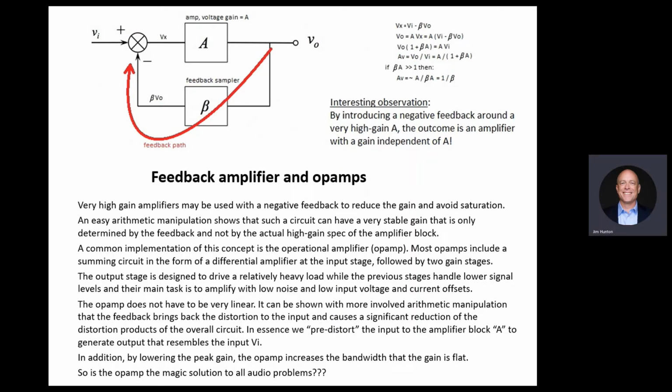All right, that difference is used to basically fix the waveform on the output. So the level of negative feedback is essentially the difference between the potential gain, like 1 million, and the actual gain, 20. So the ratio is 50,000.